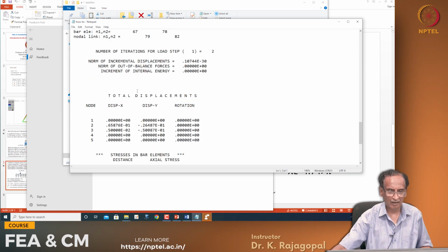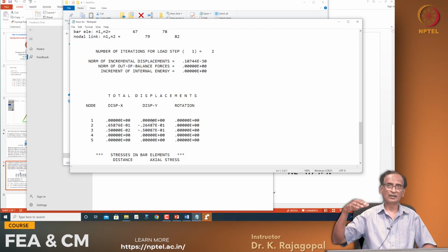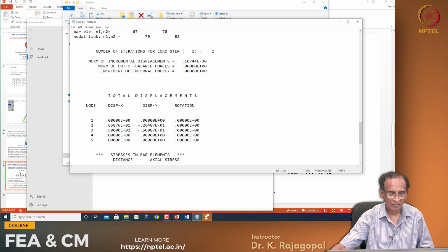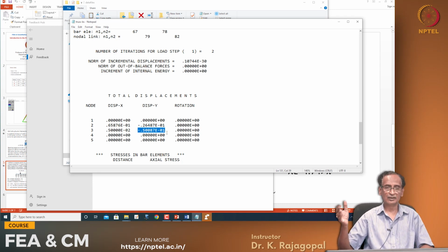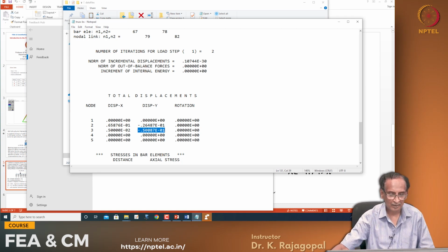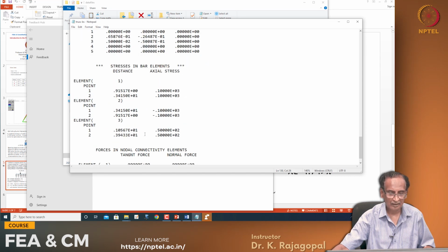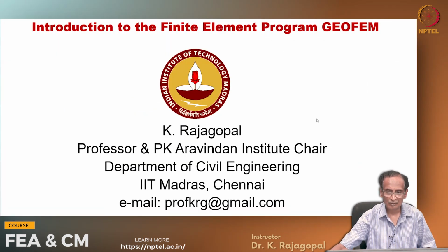So, I have given a very large stiffness and then applied a force corresponding to that stiffness, and this node has settled by the desired amount of 0.05 millimeters. That is what previously we got some 0.136, and these displacements also correspond to what we got in the classroom example. Okay, and the settlement is not going to affect our element forces, they are still the same because this is a determinate structure.